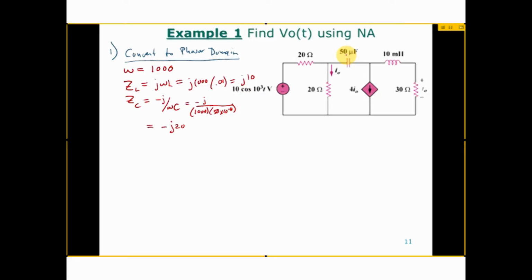Okay. What I've done in this circuit is I've redrawn the circuit in the phasor domain. Whether you want to or not, this is kind of optional, but it can help you visualize things. Initially that can be helpful, but after a while you'll realize it's really not that big of a deal. If you're going to redraw this in the phasor domain, the resistor stays the same.